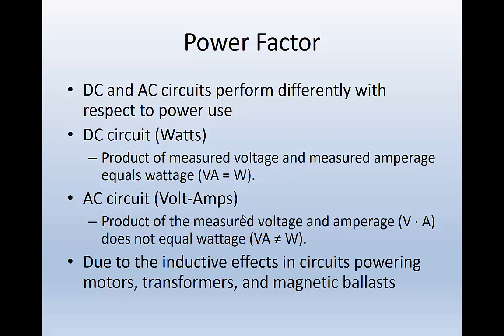Power factor we're going to talk about just for a second because we're going to get back into those peaks on the AC current. So in AC and DC circuits, they actually perform a little bit differently. In DC, remember that nice flat line, so we can say that voltage times amperage equals watts, okay? But when we get into an AC circuit, it's not exactly the same. Remember, we're not going to get that top, so we typically refer to those in terms of volt amps. Now for our class, this will be completely interchangeable, but I do need to cover this for you once.